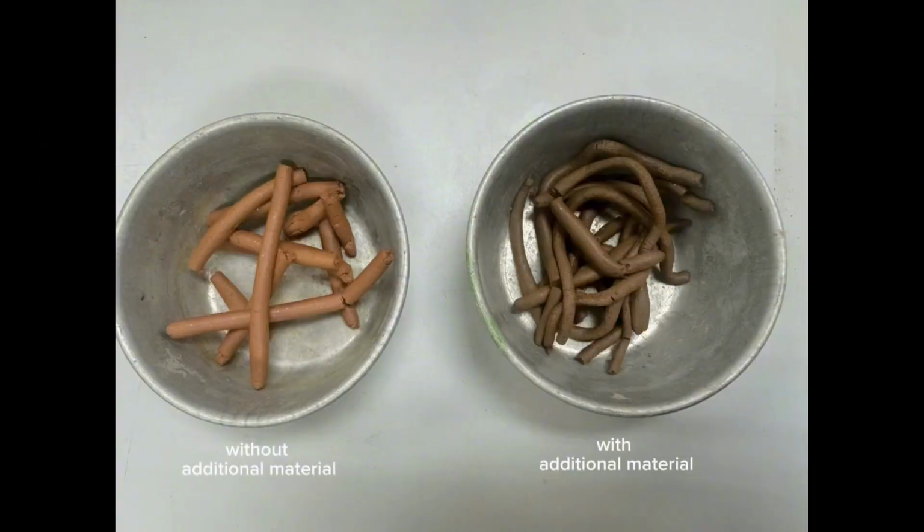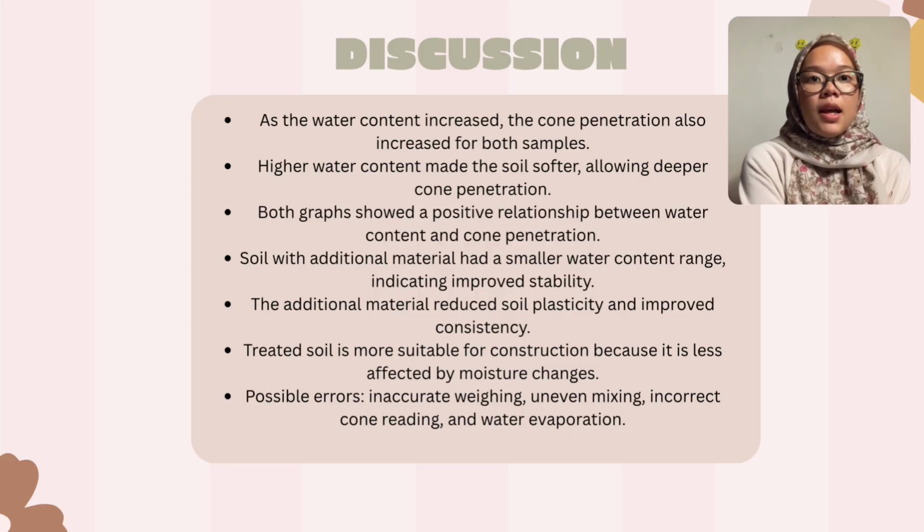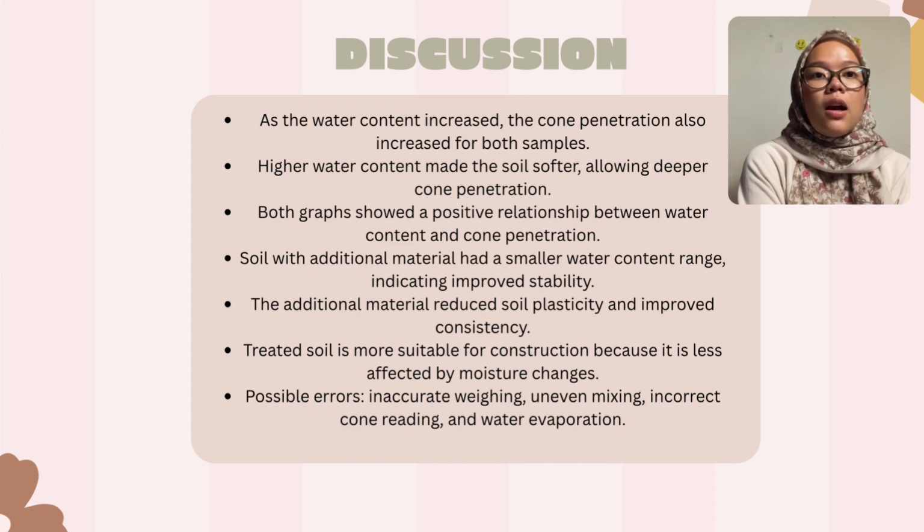Based on the result, as the water content increased, the cone penetration also increased for both soil samples. This happened because higher water content made the soil softer, allowing the cone to penetrate deeper. Both graphs showed a positive relationship between water content and cone penetration.